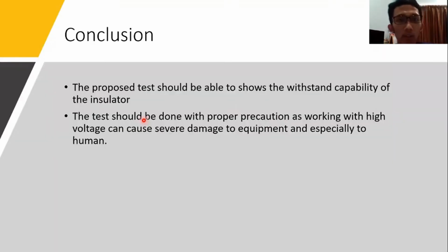For the conclusion of the high voltage proposal, the proposed test should be able to show the withstand capability of the insulator by knowing how high the flashover voltage can go. The higher the flashover voltage, the higher the withstand capability of the insulator to overvoltage.